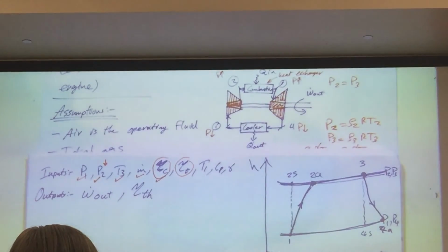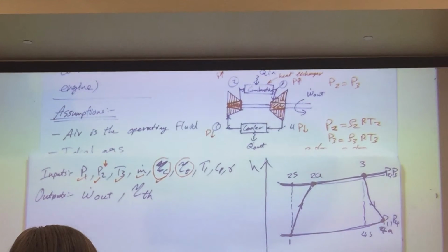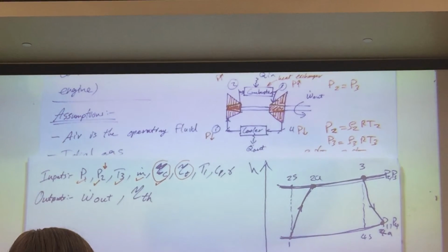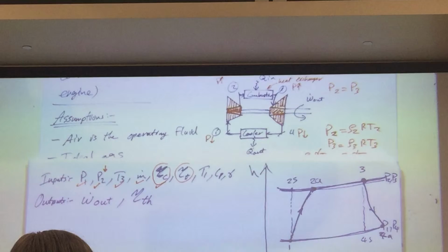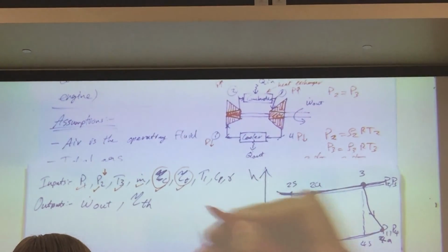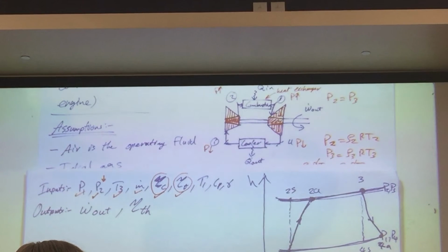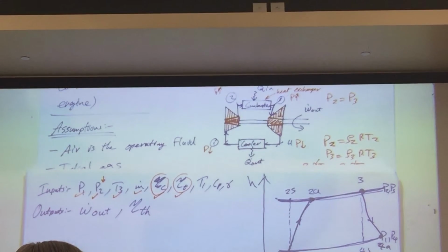So this is an input that you already know. I'm going to make my compressor 75% efficiency because I have learned in the past that having 3 to 4 stages is what gets me to 70 to 75% efficiency. So I'm going to take it at 75% efficiency. And the same thing with the turbine. The turbine is actually higher, it's in the 80s. And you're going to interact with these values in the course.